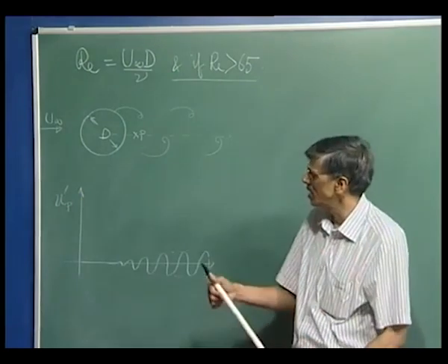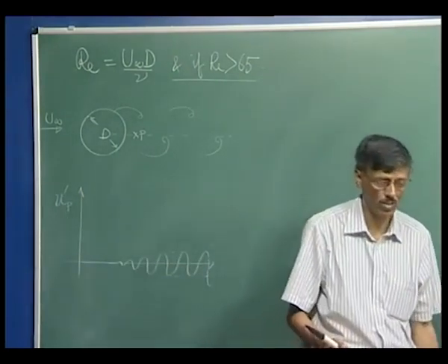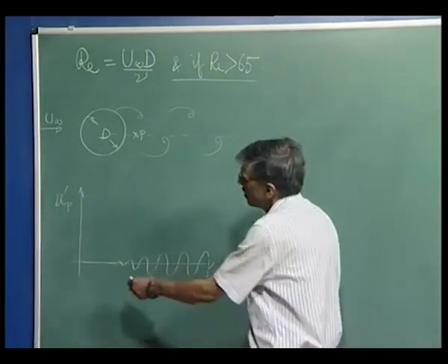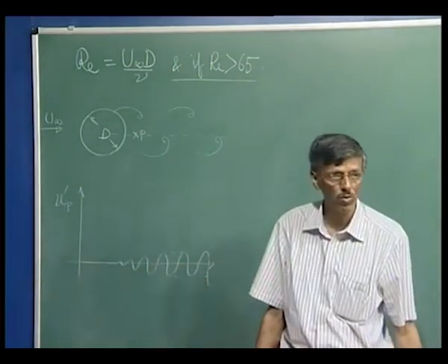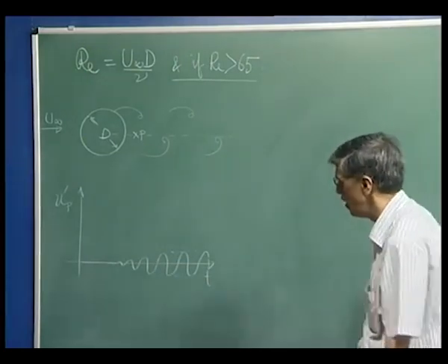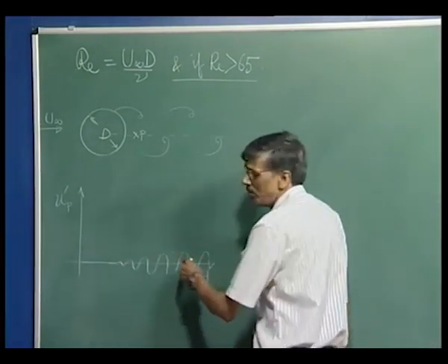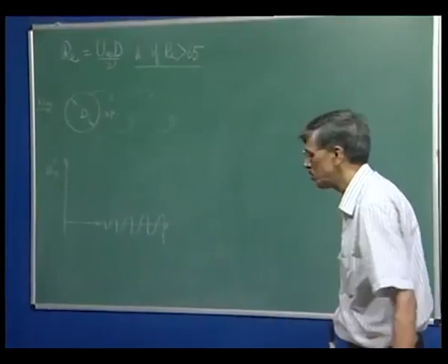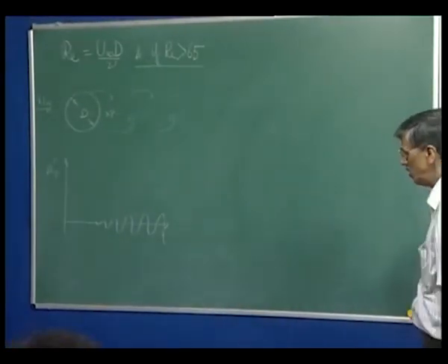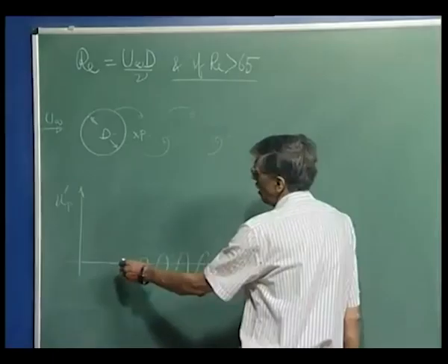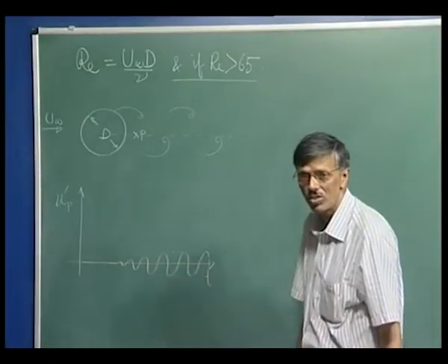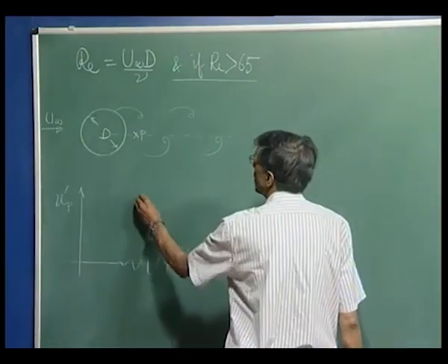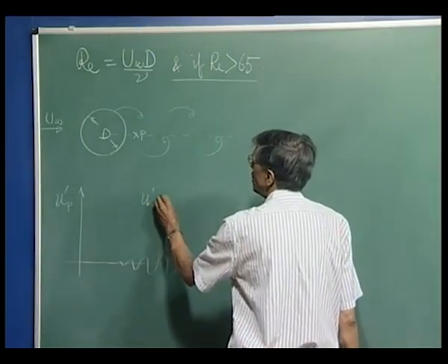So this is, let's say, a streamwise component of disturbance velocity that we have. What we notice is that this disturbance picks up slowly with time. And if you find out the envelope of this amplitude, you will find that there is an exponential growth that you are noticing. Initially, you have an exponential growth, and that actually gels with what we have been talking about in the past,